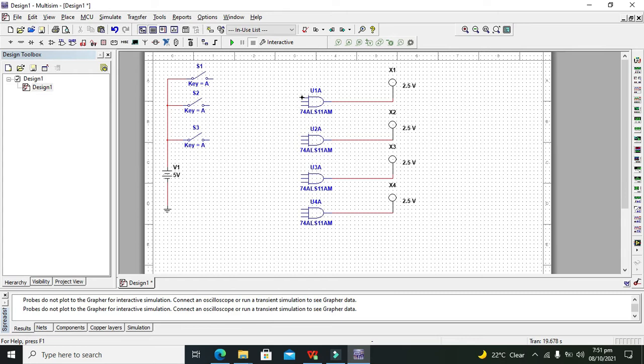Now you need to combine all the first inputs of the AND gates. Just connect them together, like this. And we need to connect the lowermost switch with this data line. So it is actually our data line now. Now what about the rest of the pins of the AND gates? We will make 4 combinations, assuming 0 0, then 0 1, then 1 0 and 1 1.